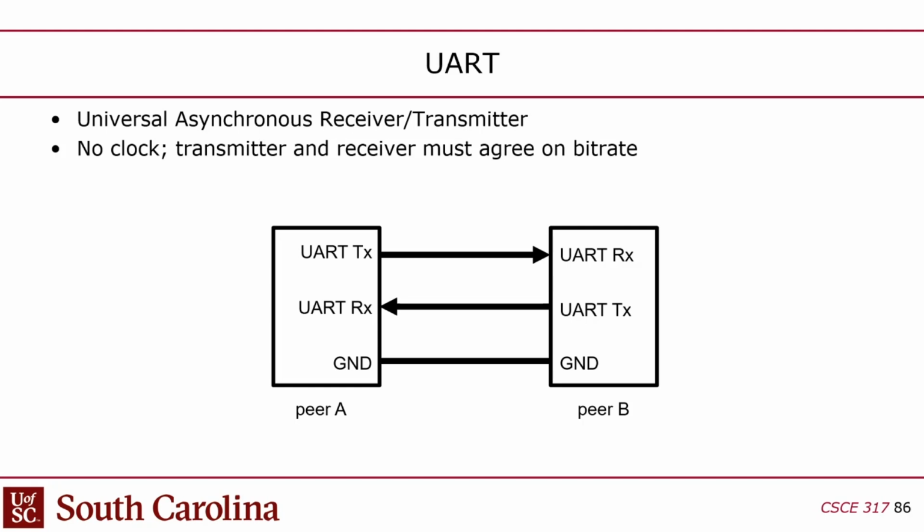And then for whatever reason, the ground is shown here, but this is kind of superfluous because SPI and I2C also, of course, assume that there's a common ground. These are electrically consistent peers on all of these channels. I don't even know that it's shown typically. I think that's why I put it in there, but you would always have a ground shared on all these guys.